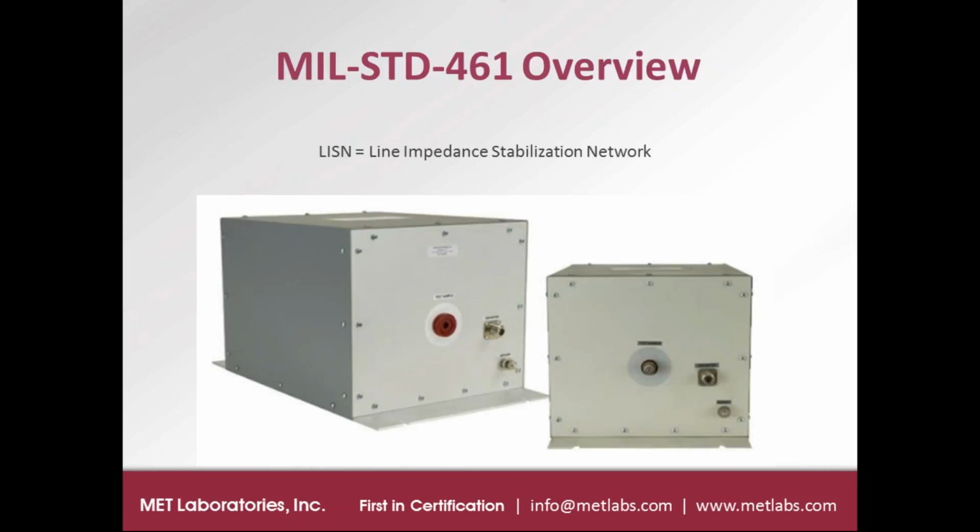Here's just a photograph of an example of some LISNs showing their design. They're mainly a shielded enclosure with a single conductor port, although there are dual LISNs that are made. And then in addition, you'll see an RF measurement port as well as a ground stud for grounding them to the chamber ground plane.